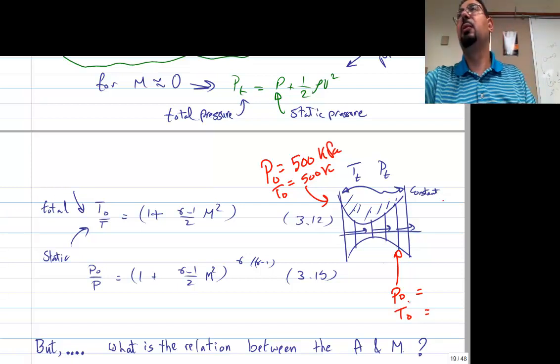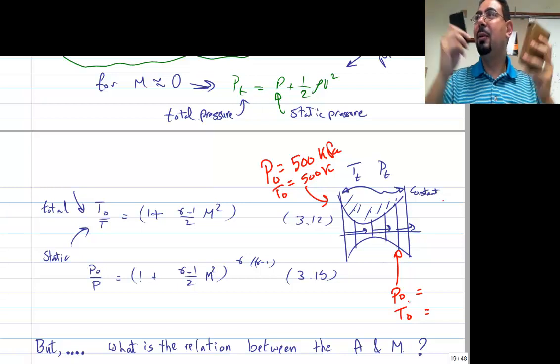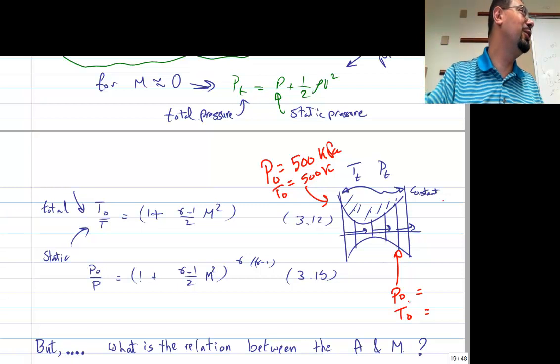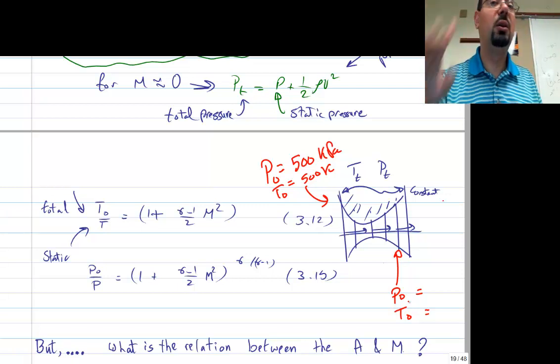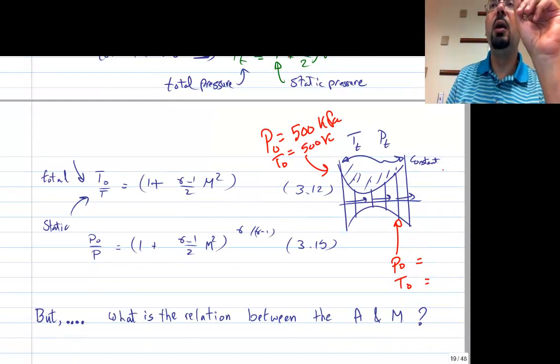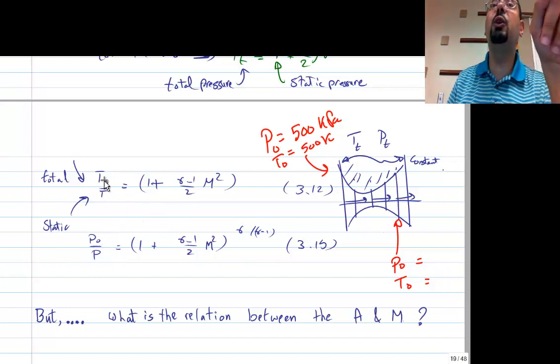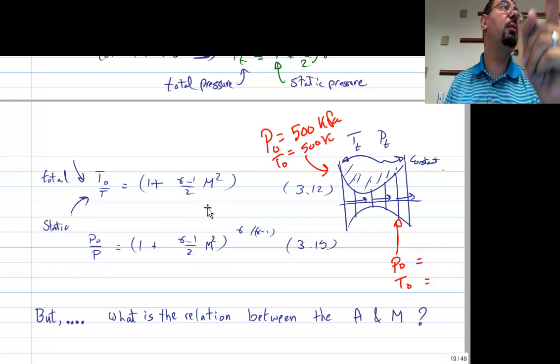But it still has the same total on it. All right? So, 1,000. We said 1,000? It still has the $1,000 on it at every location. All right? But we are very close now. Because I gave you T naught over T and P naught over P, and T naught and P naught remain the same throughout the nozzle, all you need from me right now to finish this chapter is a relation between the Mach number and the area.